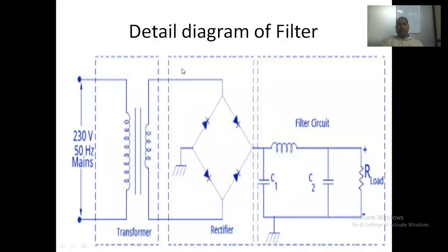Now see the second half cycle, minus is coming here, plus is coming here. Due to that plus voltage, this diode, which is considered as diode D2, conducts, so positive voltage is coming across here. At the same time, minus is coming across here. This diode's cathode is here, so it conducted, and the output comes as minus across your ground. Positive voltage comes the same way, whether in the positive half cycle or the negative half cycle. Due to that positive voltage, again this capacitor filters out whatever pulsating component there is, and it is grounded.